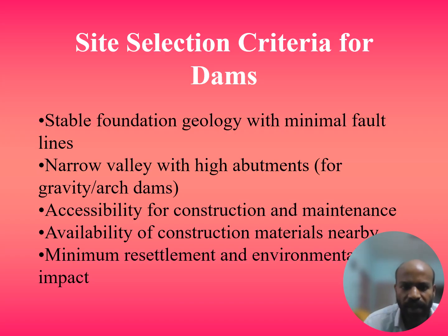First, the foundation geology should be stable with minimal fault lines. That is, the site selected should not be an earthquake prone region. And if we want to construct a gravity or arch dam, the valley should be narrow with high abutments. And the site should be such that the construction and maintenance works are carried out in the easiest way, and the construction materials are available easily from the site selected. Finally, the settlement and environmental impact should be minimum.